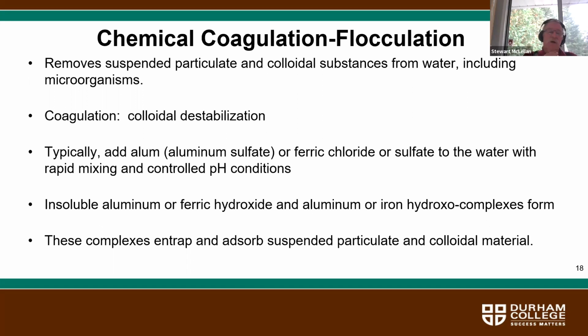The example that I give, and I've given this a couple of times, is when we look at industrial wastewater treatment processes, facilities that are discharging materials like nickel, chromium, copper, they will use a metal hydroxide precipitation process.